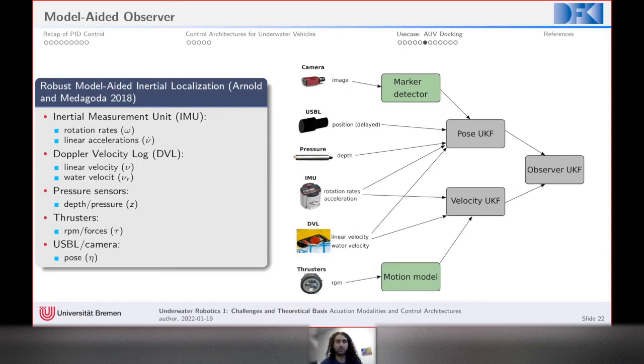If you're operating in any ocean or sea, all of the particulate matter that is floating in the water column around the vehicle will also cause acoustic reflections back. It's quite crude, so you get quite noisy data back, but you can estimate from that the water relative velocity that we just talked about earlier.